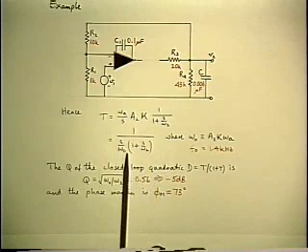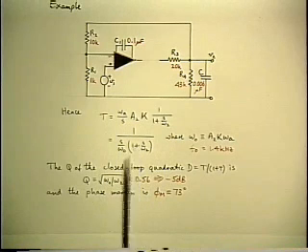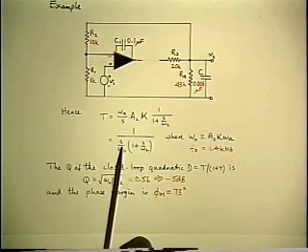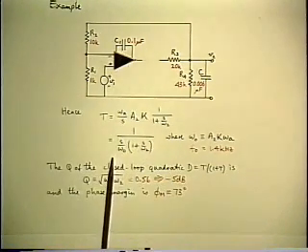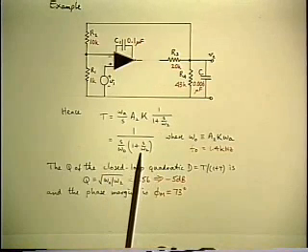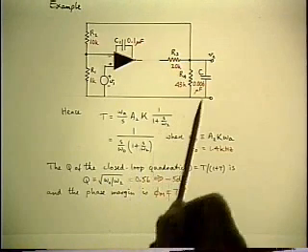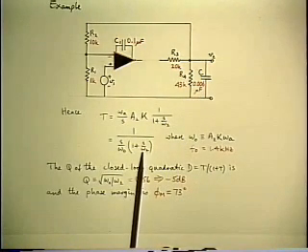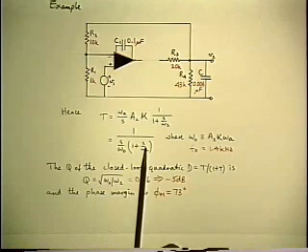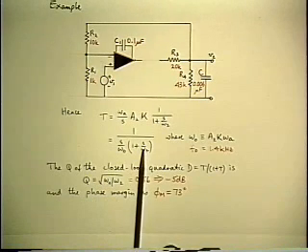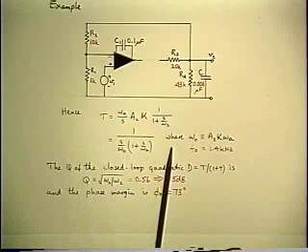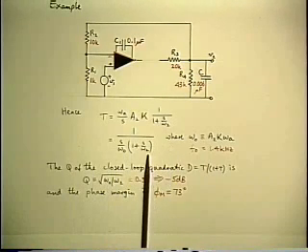And you see the format for the loop gain is exactly the same as this basic general one that we've been talking about for a while. The loop gain comes down on a single slope because of the op-amp gain, and then it has a second pole, in this case because of the external capacitor. So this is the standard form that we've already talked about. So all we have to do is look up the result we got for what the closed loop gain is going to be, and we've solved that already.